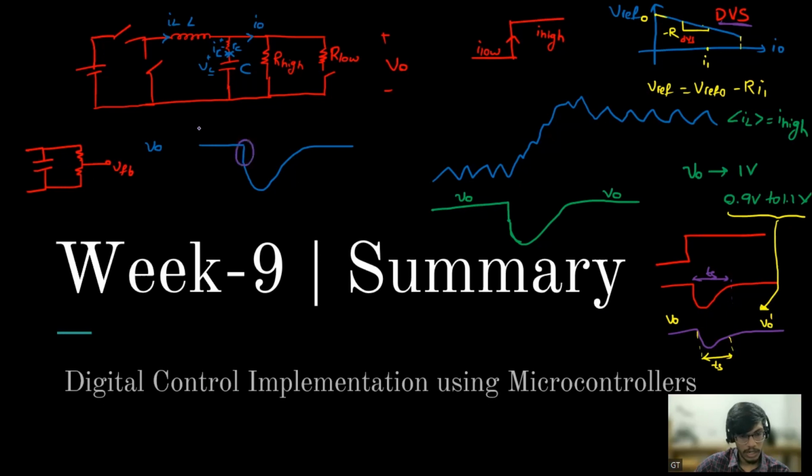The inductor current is ramping up, but it will need some time depending upon how fast we have designed the controller and depending upon the bandwidth. As the load needs that instantaneous current, the capacitor will provide it, and because of that there will be this instantaneous drop in V0. Now the capacitor will try to recharge, and the inductor will try to give the charge to the capacitor so that they can go to that new steady state.